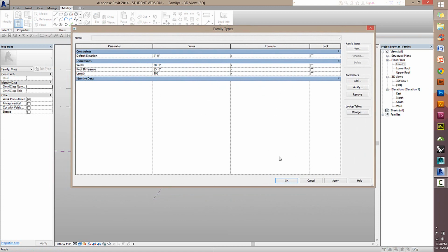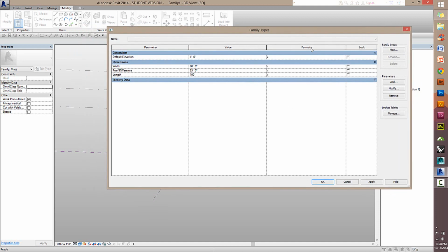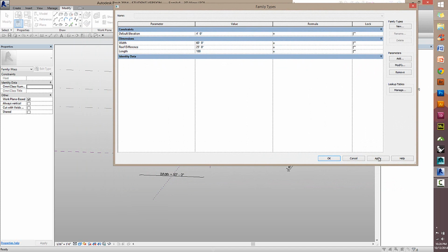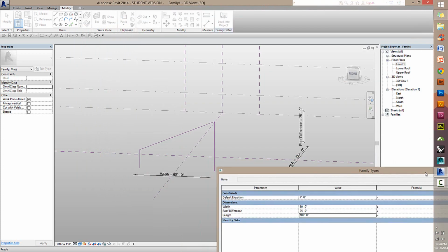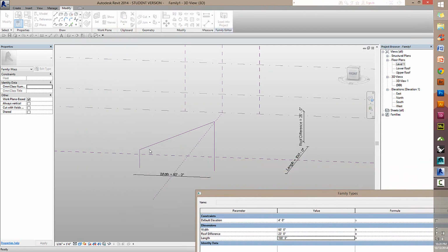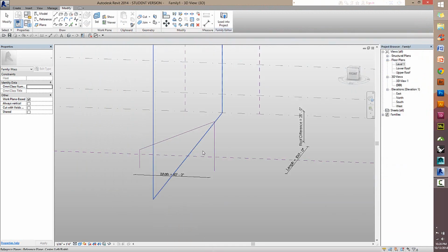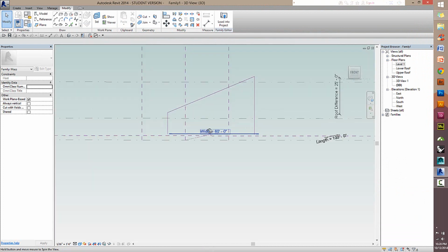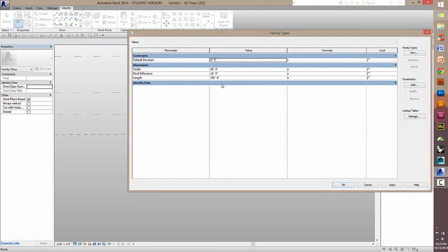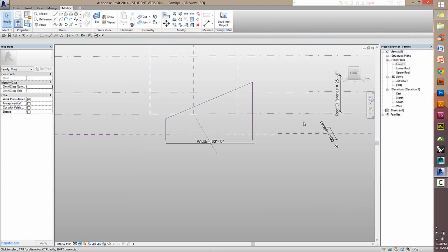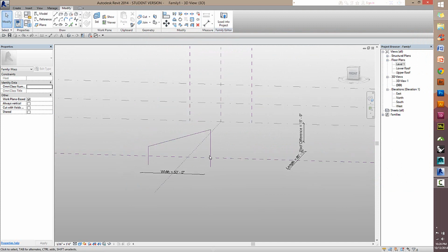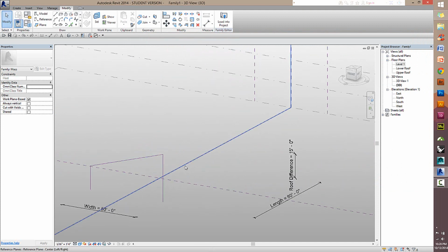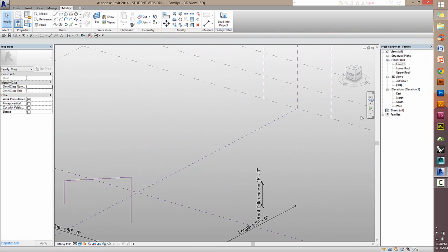To do this, you can change the dimensions and hit OK, which will apply them to your geometry and close this interface, or you can hit Apply. When you hit Apply, everything changes its position, and as you can see, everything did seem to change nicely. And then you can hit Cancel to back out without having those changes take effect, although it seems as though they did. Well, either way, if you hit Control-Z, the changes will reverse themselves, and you go back to what you originally had.